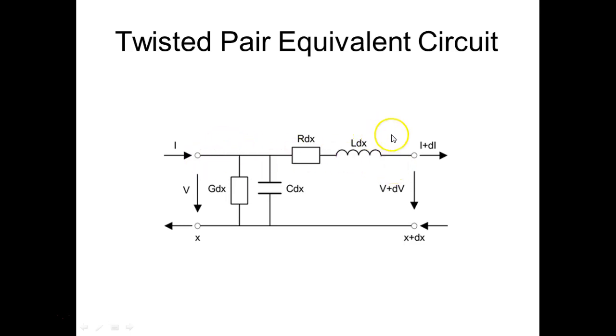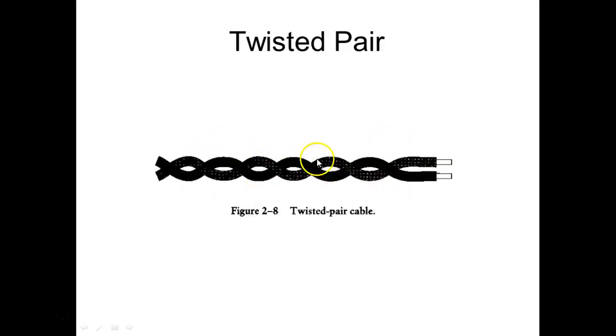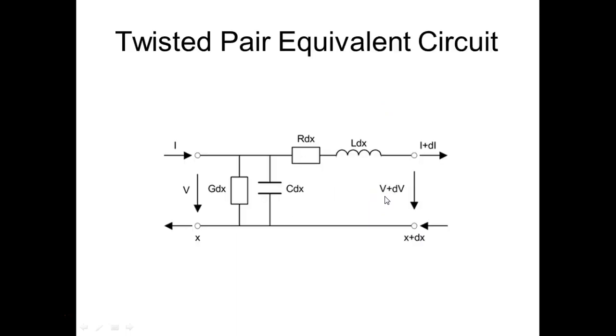And this sets up a capacitor and inductor, a capacitor between the two cables. So I've got an insulator. That's why you need to keep these twisted together. And then, of course, here the inductor is real easy to see. It's hard to see on a coaxial cable. So this is the characteristic impedance of that. Normally, twisted pair that we use in networking is a 100 ohm cable.